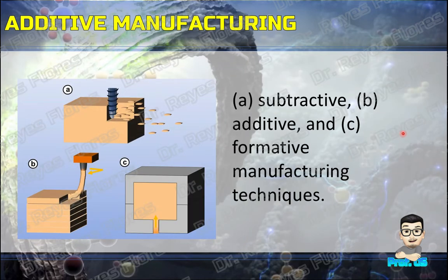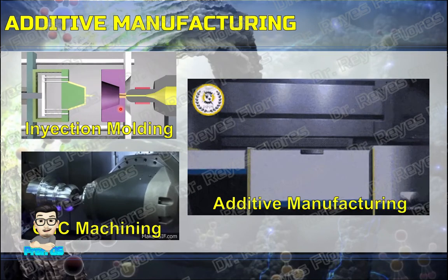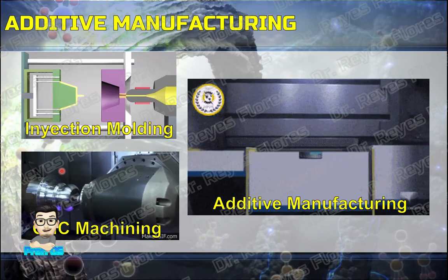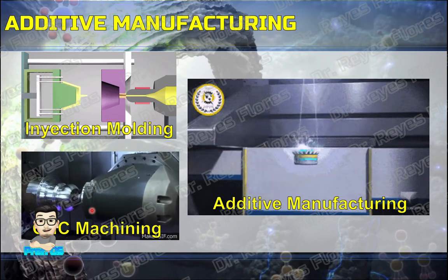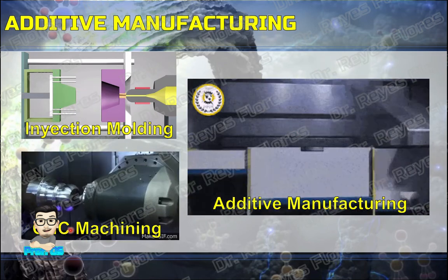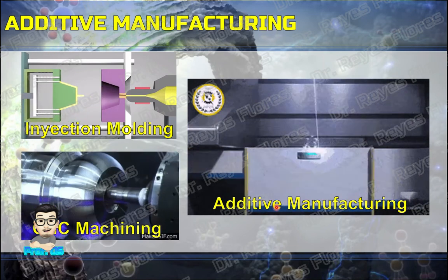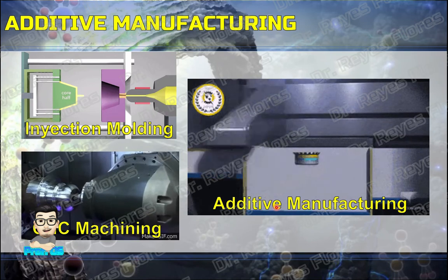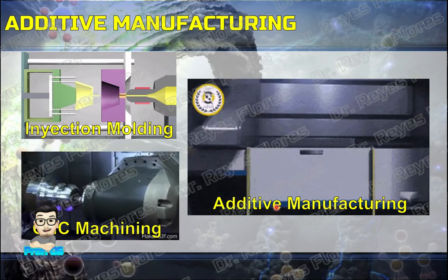For thicker layers or in demanding applications, post-processing may be used to remove support structures or to improve surface properties. As compared to conventional polymer processing by formative techniques like injection molding and subtractive techniques like CNC machining, AM is slower but enables CAD-guided fabrication of multifunctional material systems with complex shapes and functionalities including biosystems.